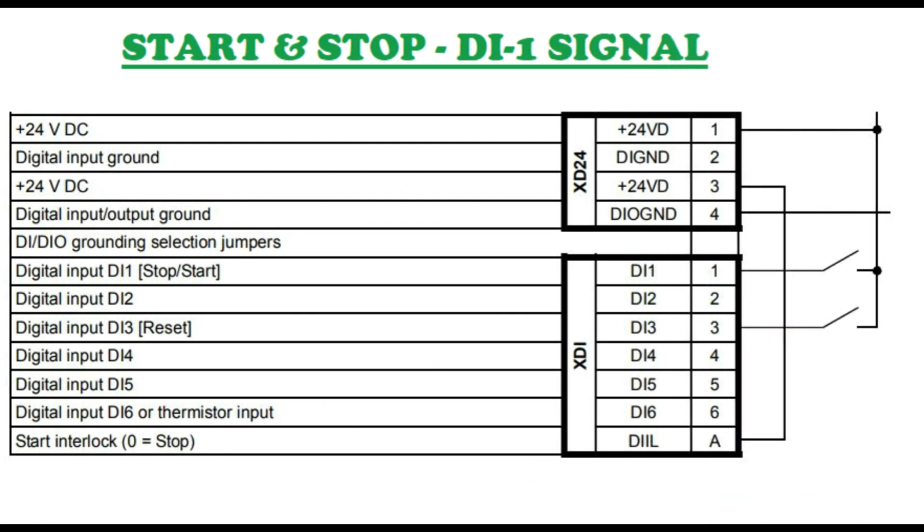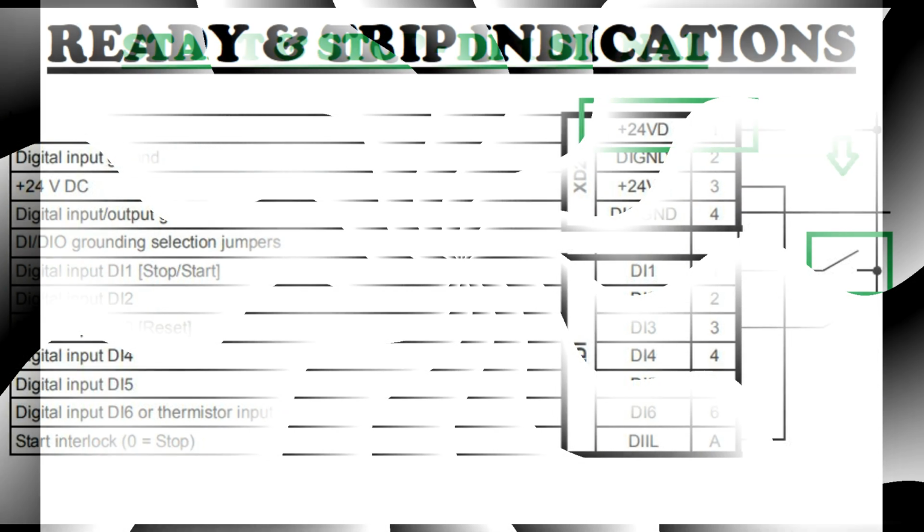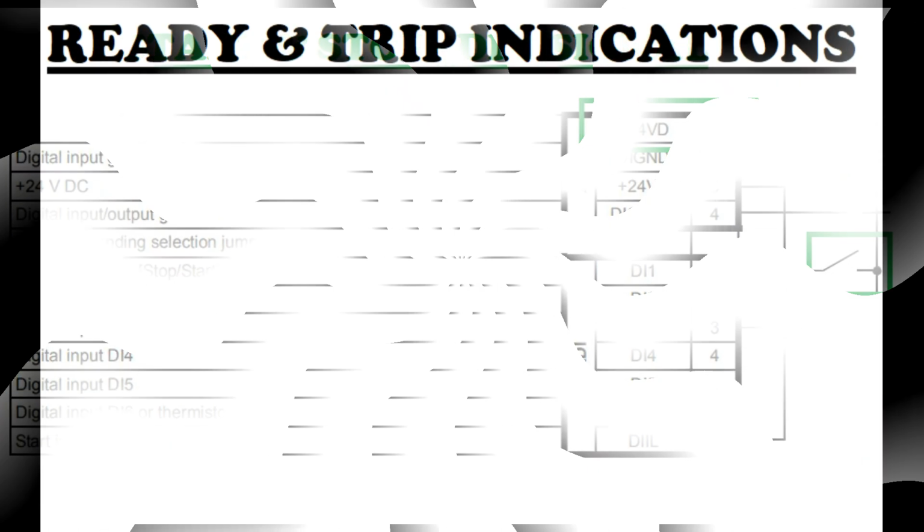We can understand properly in this. So digital input 1, on the left hand side you can see the DI block is there, and the first one is digital input 1. So the 24 volt will come here and the green color box is the intermediate relay for safety. Okay, so once 110 volt is actuated, the relay will get the command and the drive will start running.